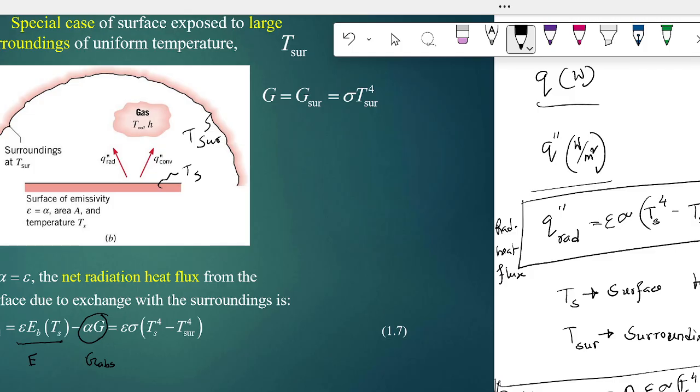Emissivity and absorptivity, when you can assume those are the same, you can say this is a gray surface. Okay, gray surface. It's a darker surface. Let me put it this way. As long as you have a darker surface, you can use this equation. But we'll be using this equation for a darker surface, lighter surface, or any surface per se. Okay, and claiming it's an assumption. So claiming this equation is true, alpha equal to epsilon.